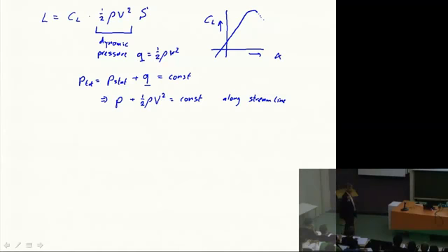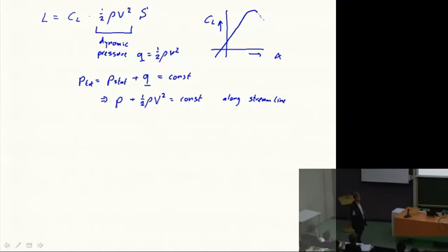So to get a feeling for what the dynamic pressure really is, it's basically the pressure that you feel if you stick your hand in the flow and you stop the flow completely. So that's called the dynamic pressure. It's a clear indicator for the airspeed.